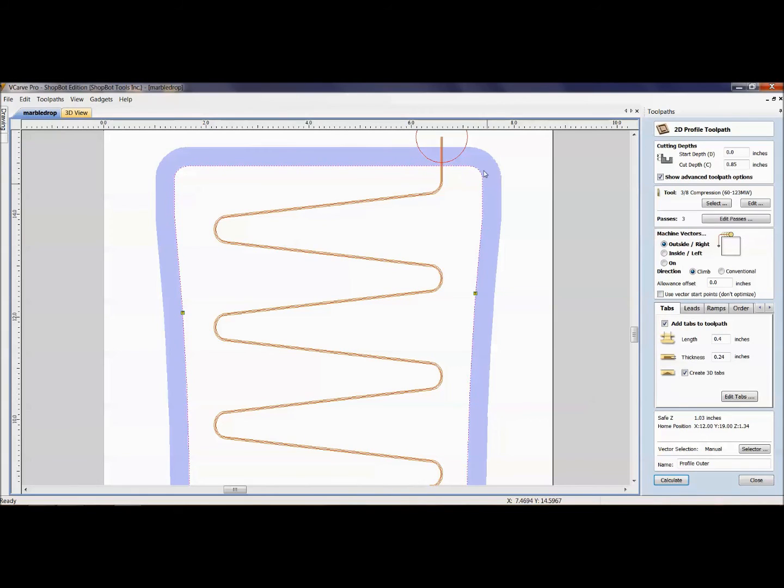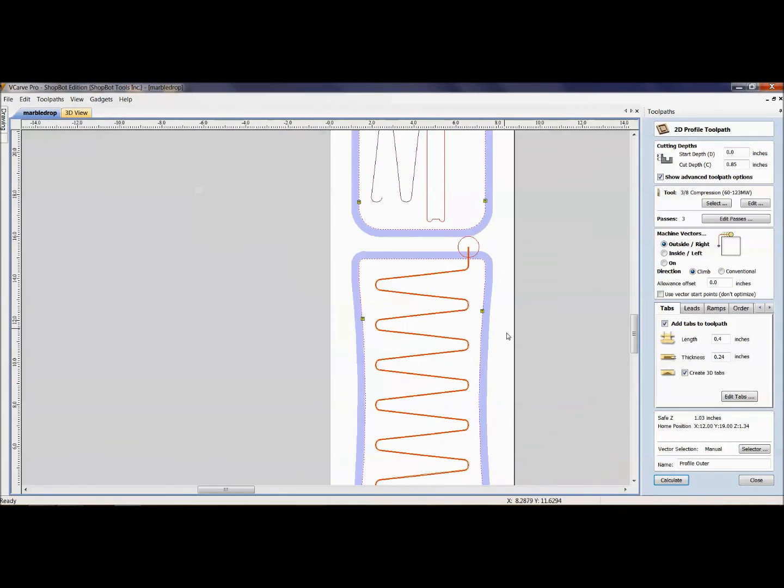If you remember earlier in the video where they were down inside of a crevice, or if they're here on a radius corner that this precision CNC has done, you're just creating more work for yourself by now trying to recreate that by hand. So these right here are real easy to nip off, walk over to the 3-inch spindle sander and clean them right back down, and no one will ever see that they were there.